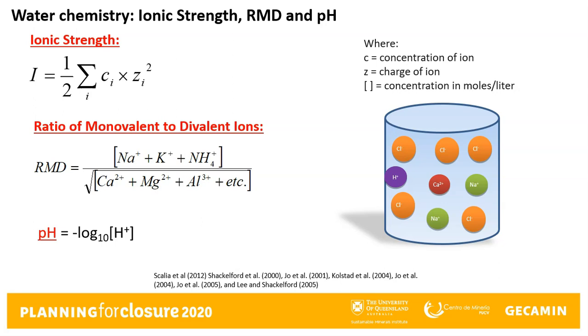And the last factor is pH. At low pH, the montmorillonite platelets in the bentonite lose some of their negative electrostatic charge density, and electrostatic repulsion is therefore reduced. As the pH is increased, the higher electrolyte concentrations can have the same effect as typical salts in that they decrease the electrostatic repulsion of the bentonite. The combination of these factors can allow a practitioner to predict the performance of the GCL against a particular leachate.